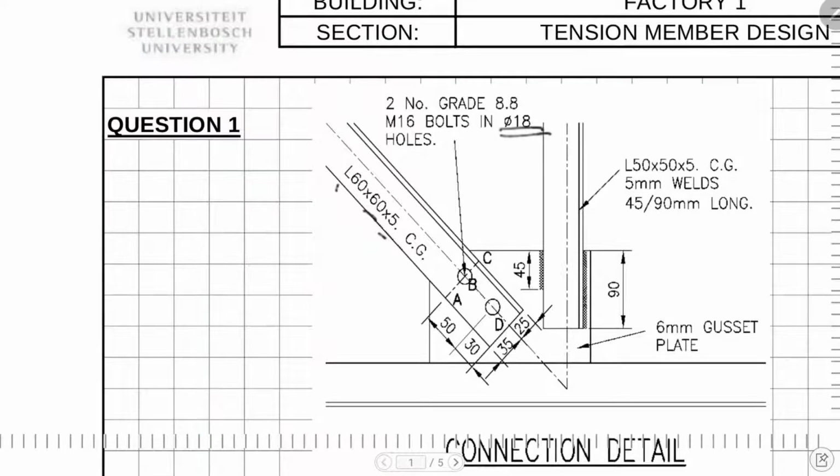So what would happen at this stage is we're trying to make sure that pretty much this entire angle does not hit yield. Because if it does, the entire thing will elongate. And even though it may not fracture, it will still cause structural problems because it's going to get longer. So we are making sure that the entire cross section is limited to yield, and it could carry more load if we test it in a machine, but the whole structure may not be able to carry it more.